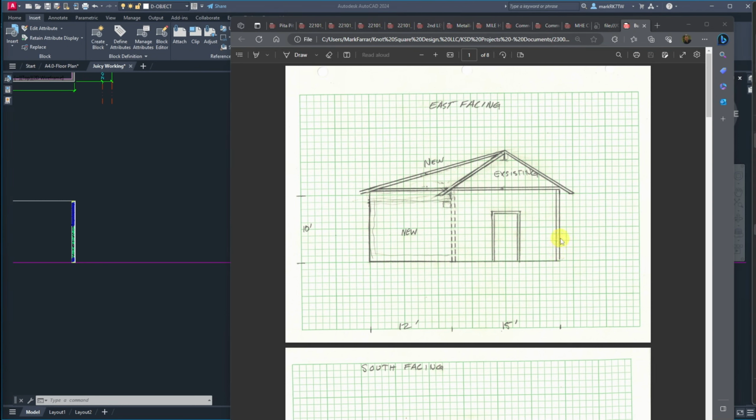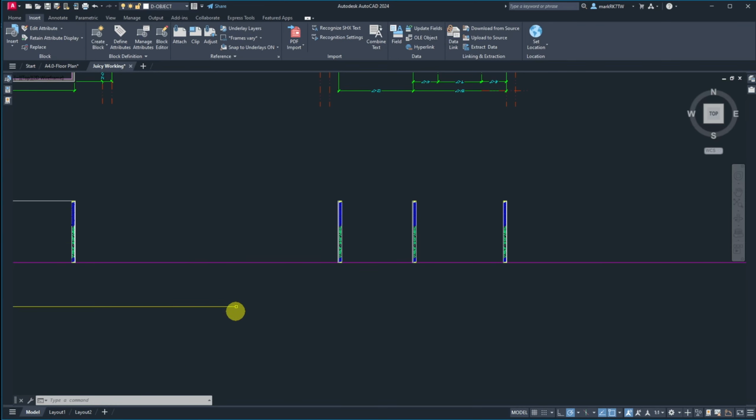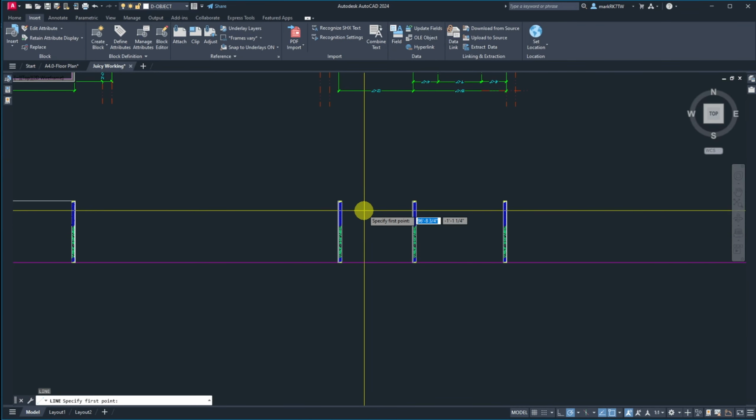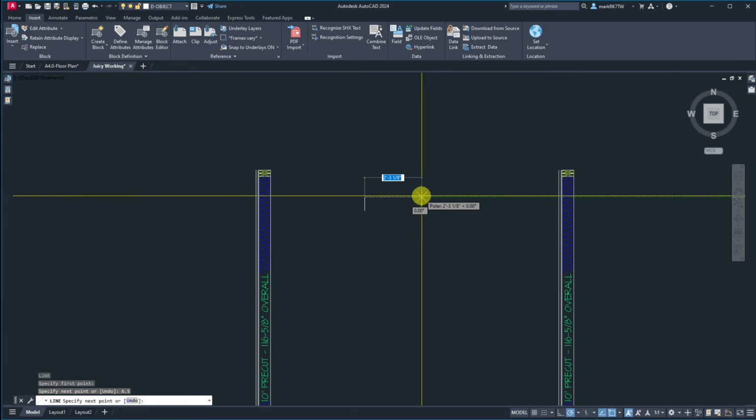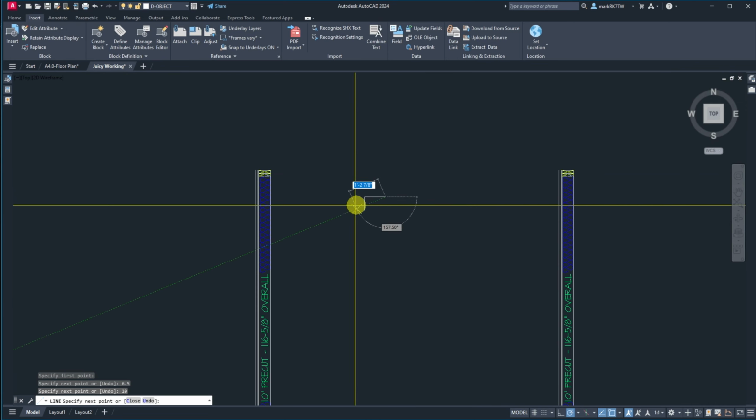So first, just going to take a count. So let's just see what we got. If I come over 10, looking at the two major grid lines, I have a drop of 1, 2, 3, 4, 5, 6, and about a half. So 6.5 in 10. Let's see how that works out in a 12 pitch ratio. So if I just do a line that goes up 6.5 over 10 and then back down,